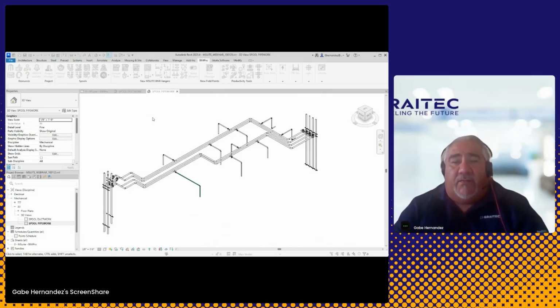So when you first install the software and set up a project with MSUITEs, you set up the project in Project Manager, and then under Utilities, you load in all of the families and parameters into that project. Once that's all done, then you'll see all of your cut sheets here, and your out of the box, or with MSUITEs at least, these custom title blocks that you can take advantage of.